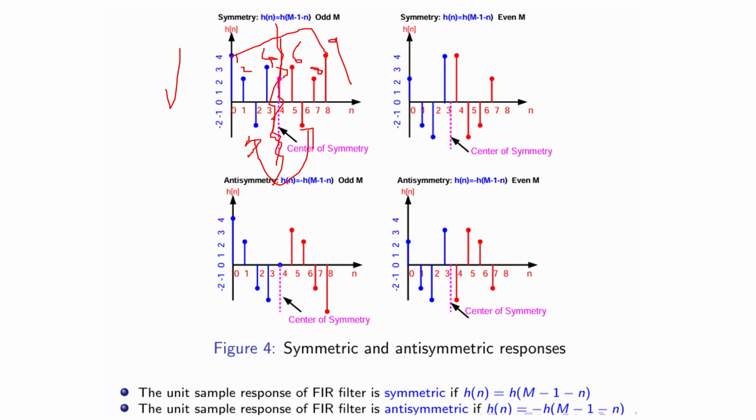So if you compute the right one and then make it double, you can get the final FIR for both left and right, the entire one. So this is the concept. Similarly, this is the center, the symmetry from the center. And so here the odd numbers are there, means total n is equal to m is equal to how much? Here m is 9. So this is why it is called odd symmetry.